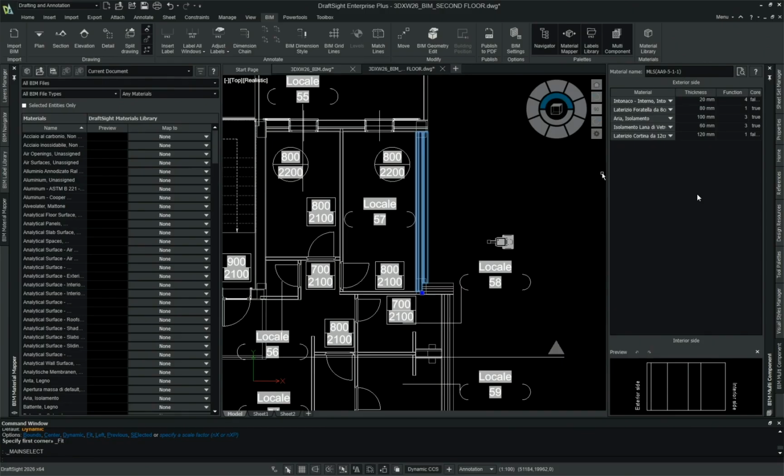So what I'm going to do is, I have it written down because I don't speak Italian. I'm going to assign the correct kind of hatching to all of these materials, and then I'll refresh the plan, and you'll see each material that makes up the wall will have a nice clean hatch on it, so it's easy to understand what each wall is.